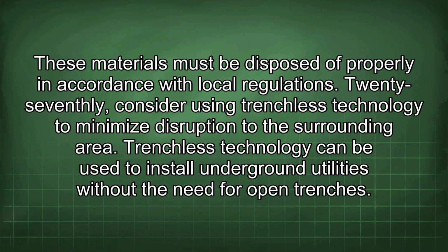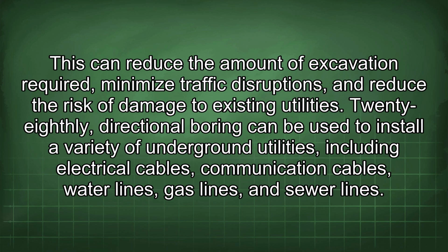Twenty-seventh, consider using trenchless technology to minimize disruption to the surrounding area. Trenchless technology can be used to install underground utilities without the need for open trenches. This can reduce the amount of excavation required, minimize traffic disruptions, and reduce the risk of damage to existing utilities.